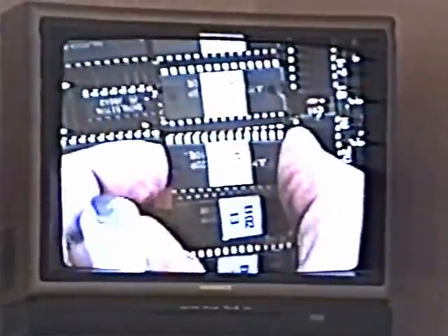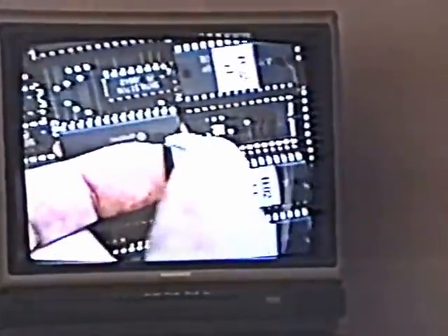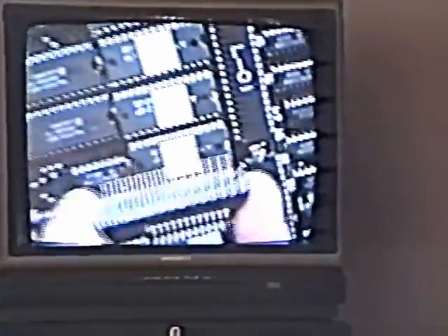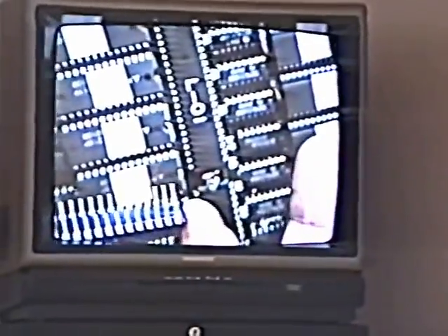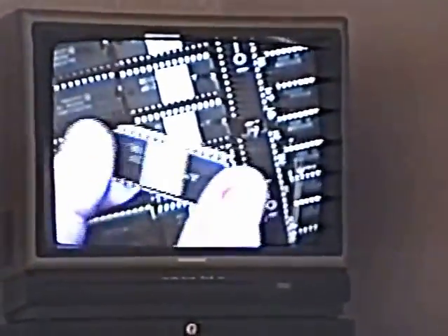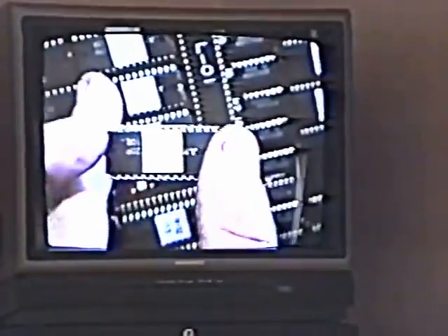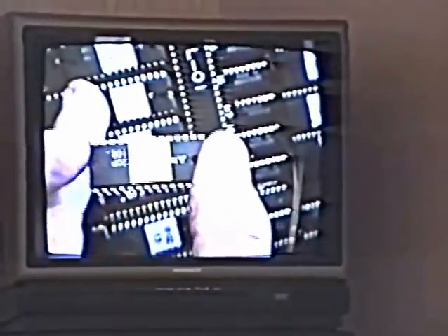Carefully prying it up. Never, under any circumstances, try to pull one of these chips out with your hand without a screwdriver, because you'll get one end loose, it'll go up like this, you'll bend the little pins, and maybe if you're lucky you can bend them back once. But if you break a pin off, these integrated circuits are custom integrated circuits. They're called ROMs, read-only memory.